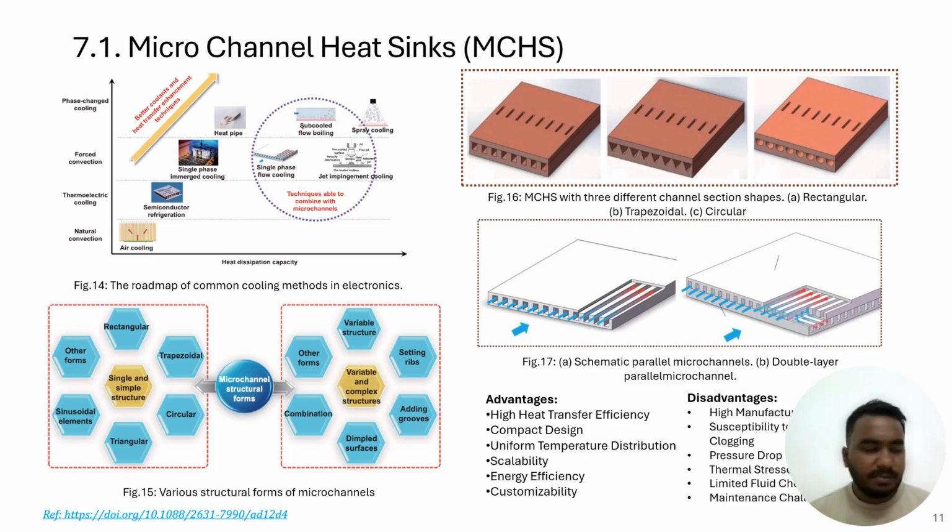So there are advantages and disadvantages. Coming to the advantages: high heat transfer efficiency, compact design, uniform temperature distribution, scalability, energy efficiency, customizability. And now coming to the disadvantages: high manufacturing complexity, susceptibility to fouling and clogging, pressure drop issues, thermal stresses, limited fluid choices, and maintenance challenges.